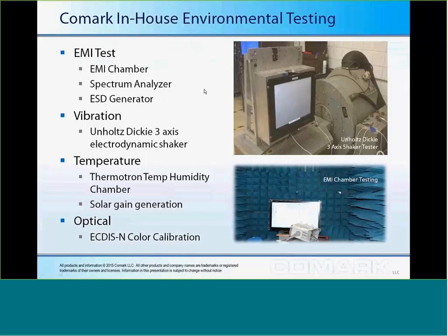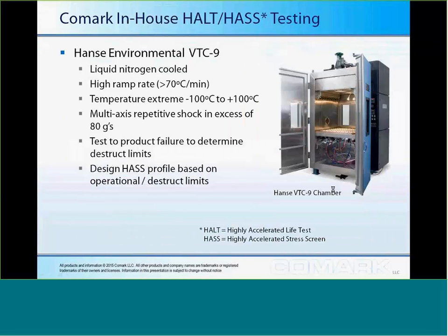Full complement of testing. We have an EMI test chamber, vibration, temperature. We have a color calibration. We have an anechoic chamber. And one of the crowning glories, because we've done military items, is a HALT-HAS testing. If you're familiar with that, it's temperature and humidity and vibe all in the same time. It's required for a lot of mil-spec items. You can see it can go very temperature extremes from like minus 100 to 100, and it can do repetitive shock while it's in those temperature ranges.